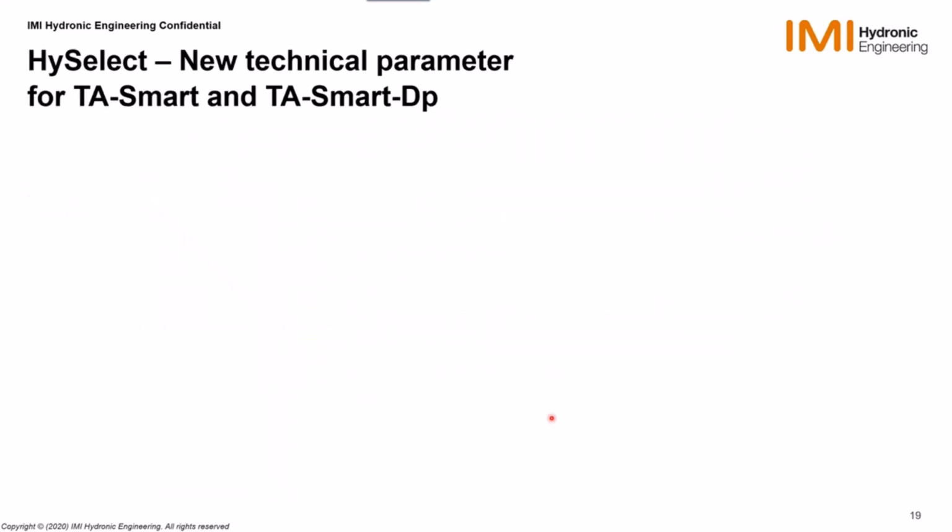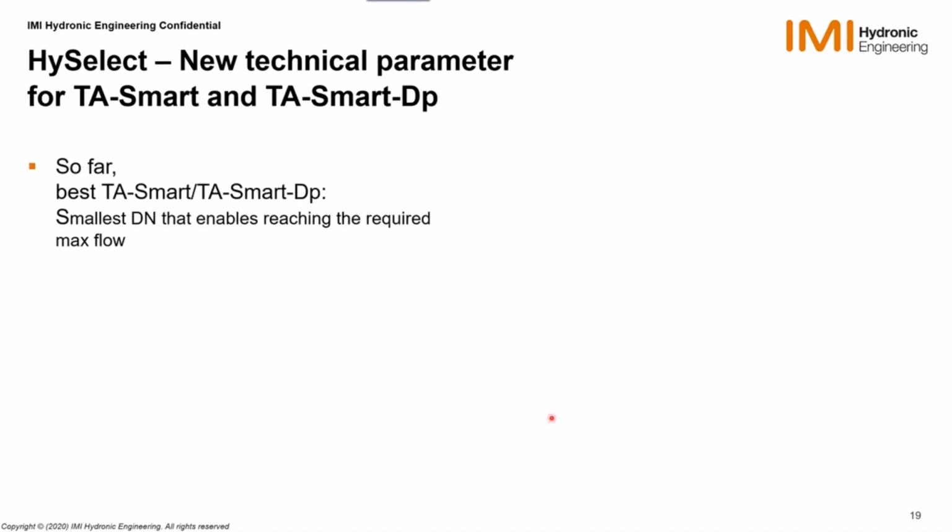Next is about the selection of the TSMR and TSMR-DP. I need to let you know that there is a new parameter that will come in. So far, the best TSMR or best TSMR-DP, we have defined as the smallest DN of the valve that enables reaching the required max flow, correct? That can lead us to delta P that are up to 35 to 40 kPa.